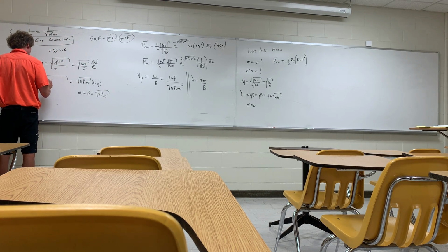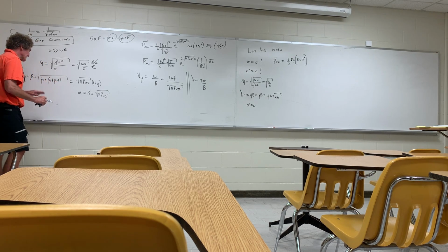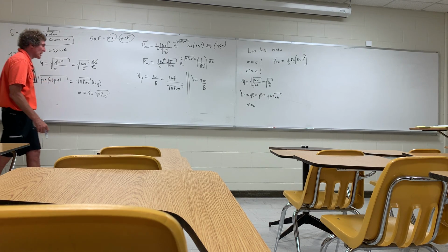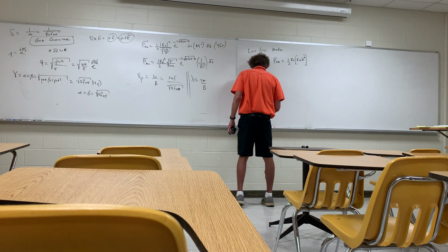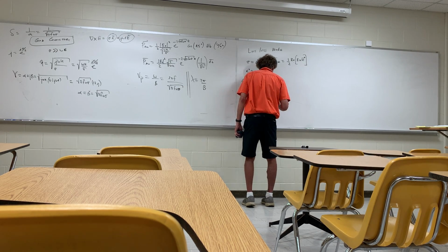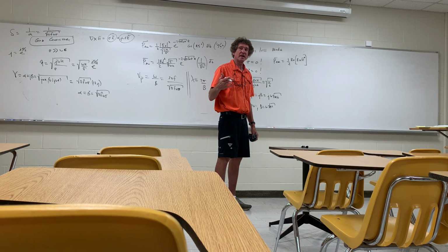If you had done this plus j omega epsilon, if you got rid of the sigma in this case, you got j omega squared, square root of, you bring out that j omega and you have square root of mu epsilon. That's what that is. So this means that beta itself is just equal to omega square root of mu epsilon if it's lossless. Do y'all follow me? And again, I'm just pointing out facts.